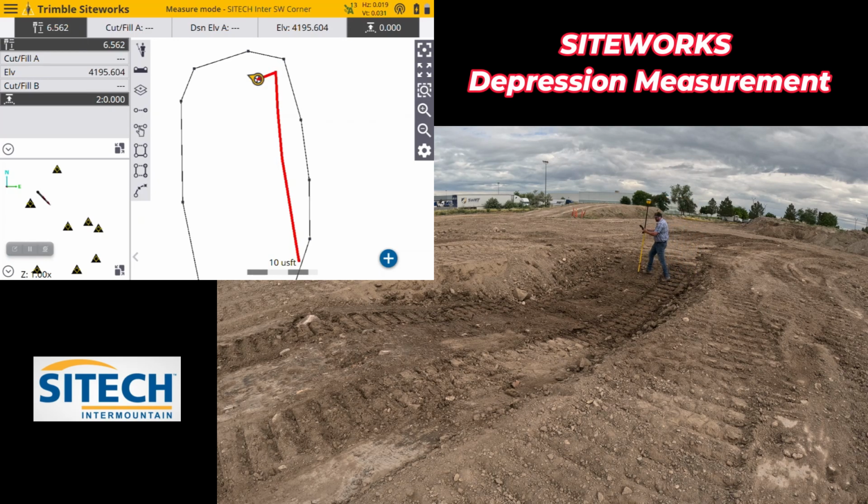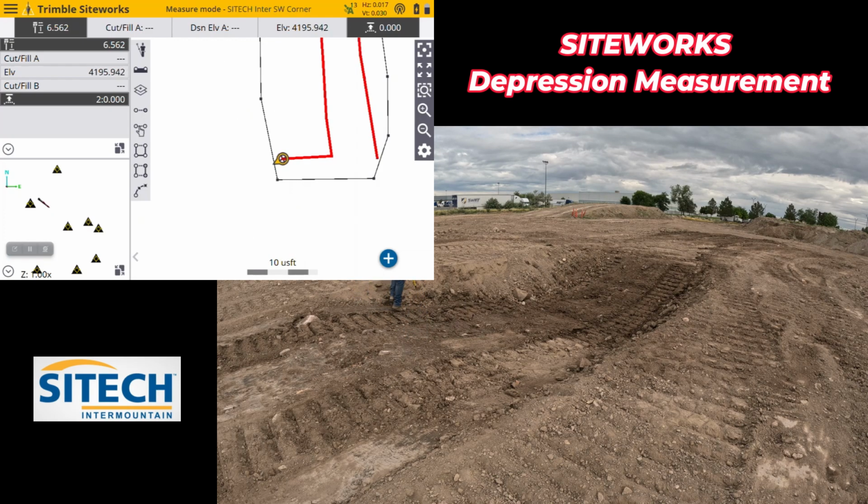At this point, since it's pretty well straight across, what I'm going to do is just jump over to the middle here. Take a couple shots down through the middle. It probably doesn't matter as much, because it would have gone from that line to that line and made a flat floor. But just to make sure, I've always said that if you're not going to fly it with a drone, because a drone's going to get millions of shots and points in a point cloud, the more and more shots you take with the data collector, the better. The better number is going to come out.